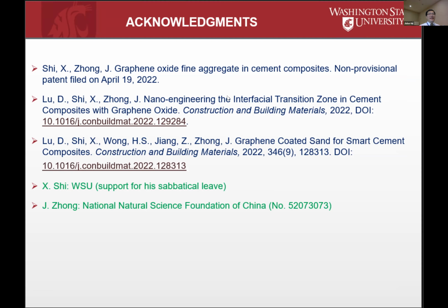So my question is about the mineral of the fine aggregate. Very good question. In this case, the force is truly the Van der Waals force. The beauty of this technology is that it can serve as a platform for many different types of aggregates. Traditionally, you could use recycled concrete aggregate, which is more absorptive, or you can deal with a very smooth surface, which is very chemically inert. Doesn't matter. It will grab onto this sand particle and hold on really tight because it's such a strong force at the nanoscale. Of course, there will be variations, but all of them should work.